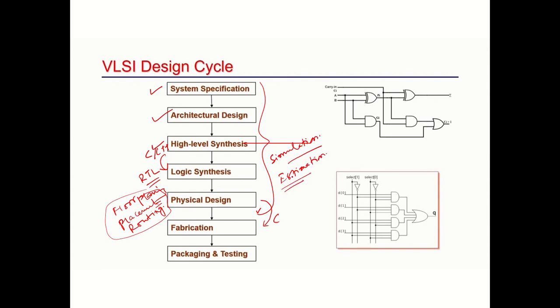So here, what we used to do, because fabrication actually costs a huge amount, and it is also not possible to fabricate all the devices. So we estimate first, and finally, when everything is final and fixed, then we go with the actual fabrication. From the physical design, we give the GDS2 file to the Fab Labs, and they fabricate the module with the help of this GDS2 file.